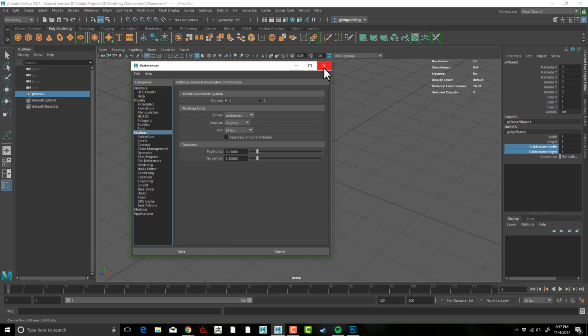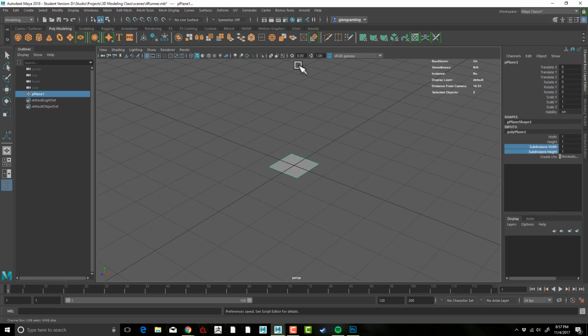The issue is that whenever you jump to say a 3D printing software, if your units are set to feet, so say you have something that's 5 feet by 5 feet, and you move that to a 3D printing software, the type of unit doesn't get saved in your file, just the number of units gets saved.